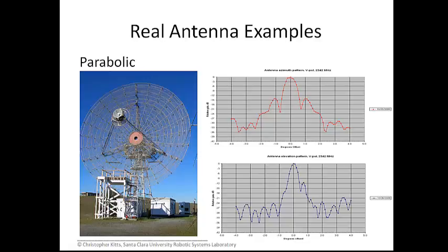So at the 0 relative dB point, that's the peak power coming out of this in a directional sense, and that's really overall compared to the isotropic standard, 45 dB. But you can see how this drops off, and you can see that within 1 degree, we're many dB down from the peak. And remember, 3 dB is one half of a drop. 6 dB is 1/4. So you can see how dramatically this drops off.